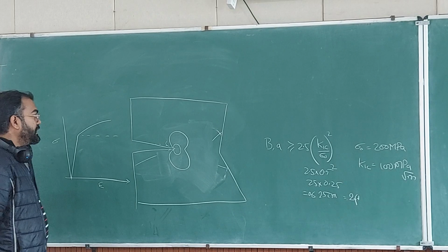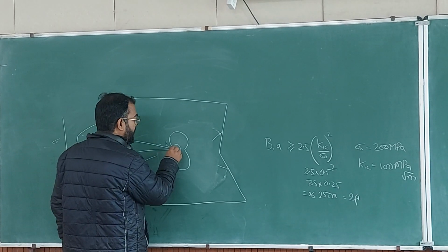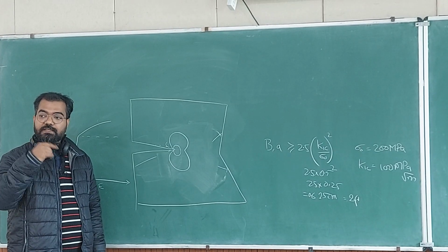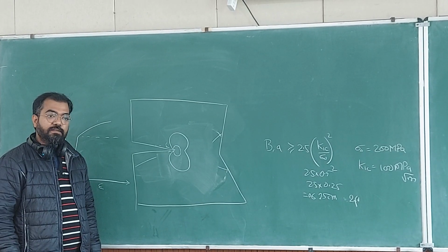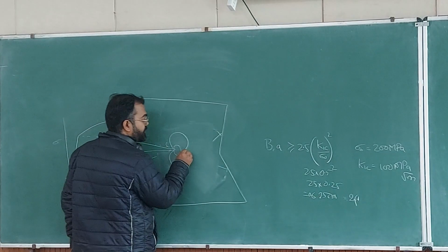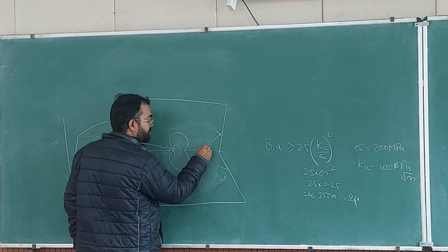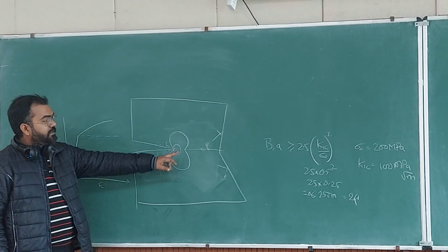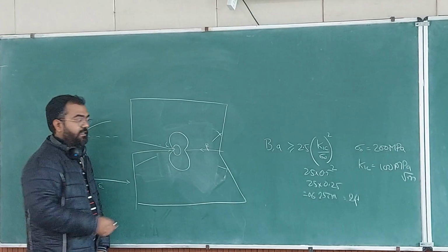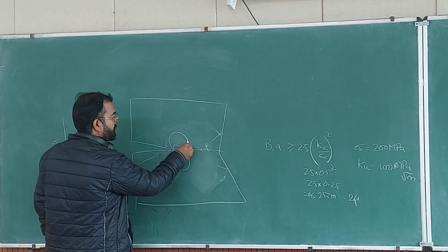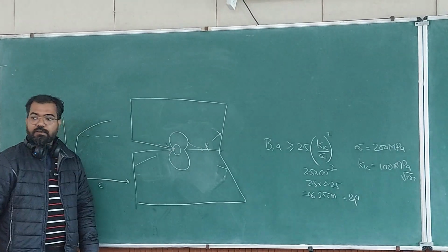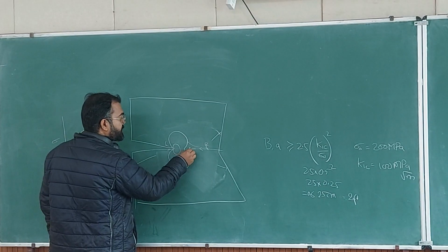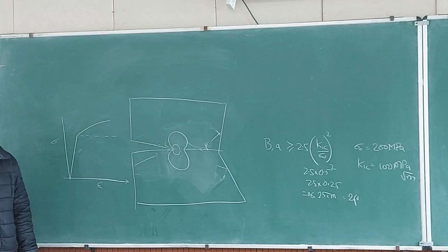Okay, so there is a zone where what will be happening now? So at crack tip, what is happening? So there is a region where plastic deformation is happening. So you see, if you proceed along this path, then you have stresses increasing, okay? And then you reach here and you hit sigma naught, okay? For theta is equal to 0, you will be hitting sigma naught here, okay?